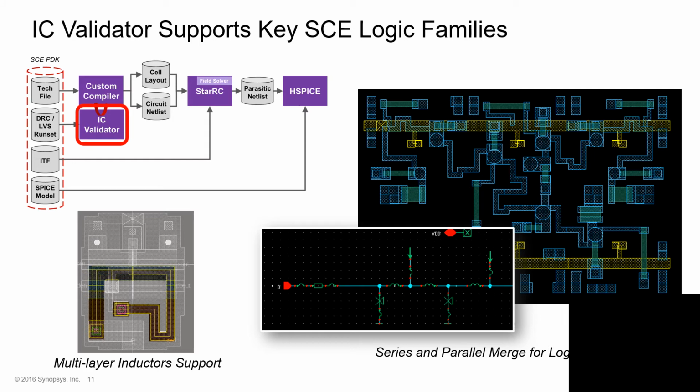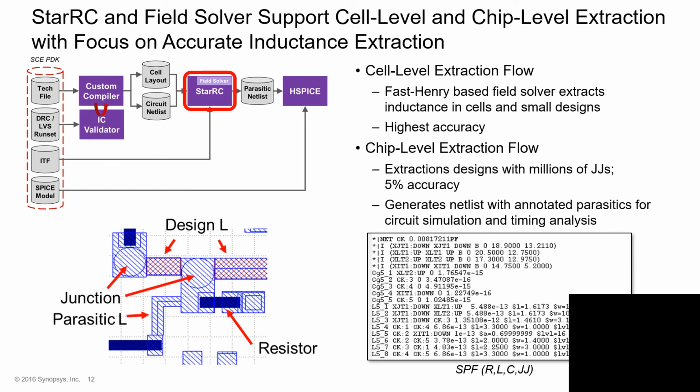Here, everything is very similar in terms of schematic versus layout to what you're familiar with in CMOS, with one minor exception: inductance extraction is very tricky because, unlike capacitance, which is really contained in terms of next-door neighbors, inductance is a long-range feature, and many inductors cover multi-layer interaction, so you need accurate extraction for that, and you need quite intricate field solver behavior, and the way in which you do the meshing and the realization is pretty important.